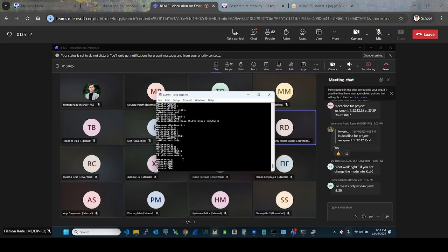All the values that you are working with inside the embedded platform are integers. So in this case, we are using 150 for 50 degrees, because it's more efficient to use only integer numbers instead of floating numbers. You will have an instant feedback if you are using integer numbers. Let's set the steering back to 0.